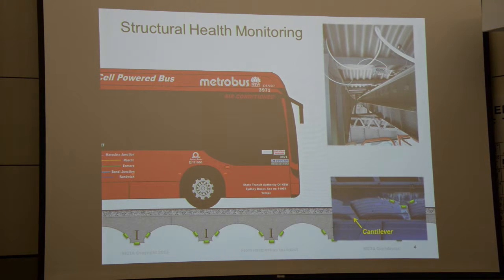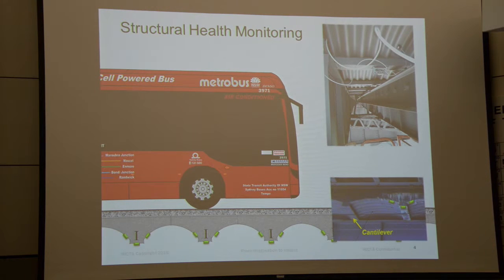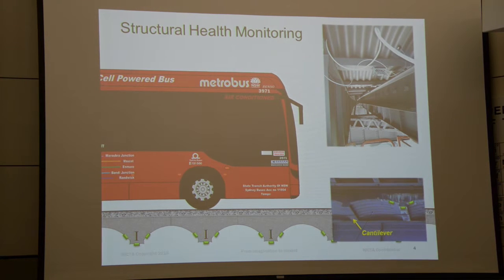So this is about 2 years ago. It started as a research project, more or less. There was no hardware available in the field, in the market to do this cost effectively. There's 2,500 sensors on the bridge. They're accelerometers, they're MEMS accelerometers like you have in a mobile phone, so they're quite noisy, but they're good enough, and we can overcome some of the limitations with these sensors through software.